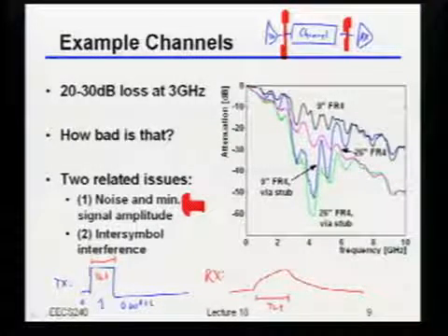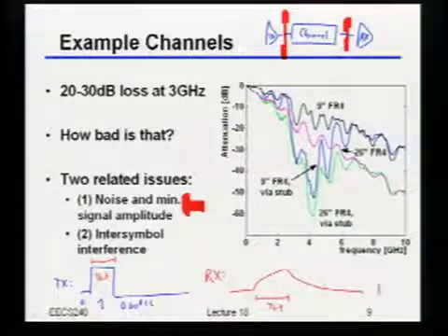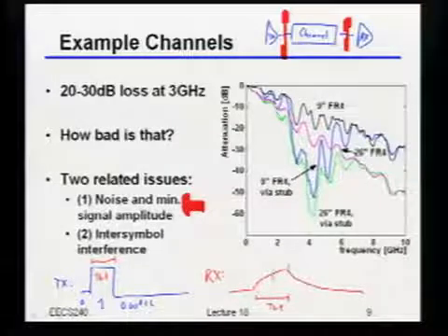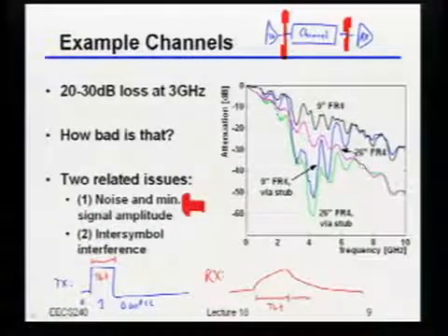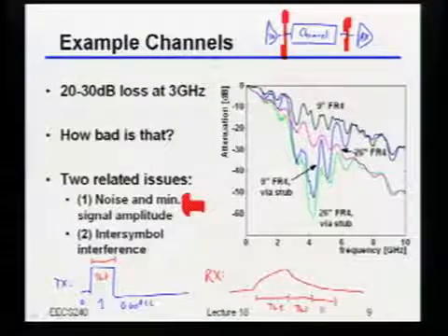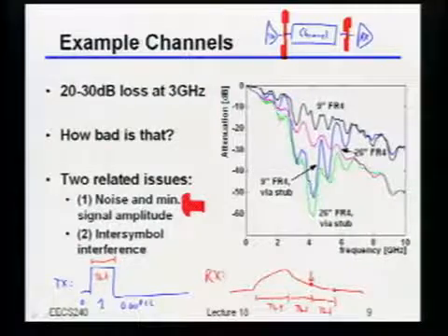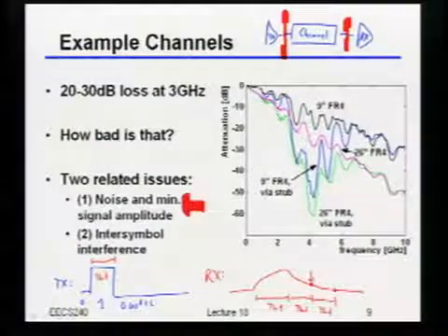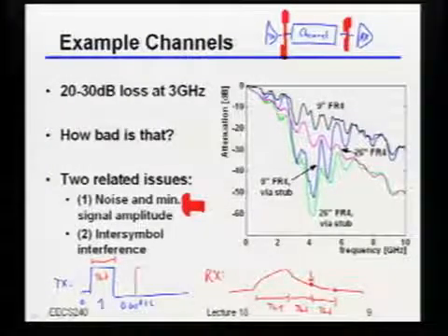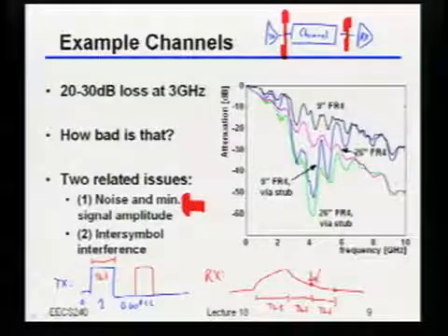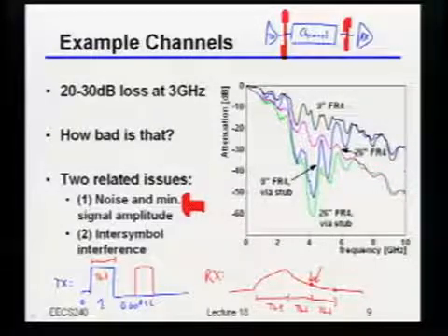this thing was supposed to be just exactly either a 1 or a 0, right? But when it shows up at my receiver over here, not only will I not necessarily get the same height as what I transmitted, but actually, for some number of bits later, I'm still going to have some amount of voltage left over from that previous bit that I sent, right? That's bad news because if I was instead going to try and send another different bit over here, this leftover voltage is kind of going to screw me up. It might actually push me in the wrong direction.